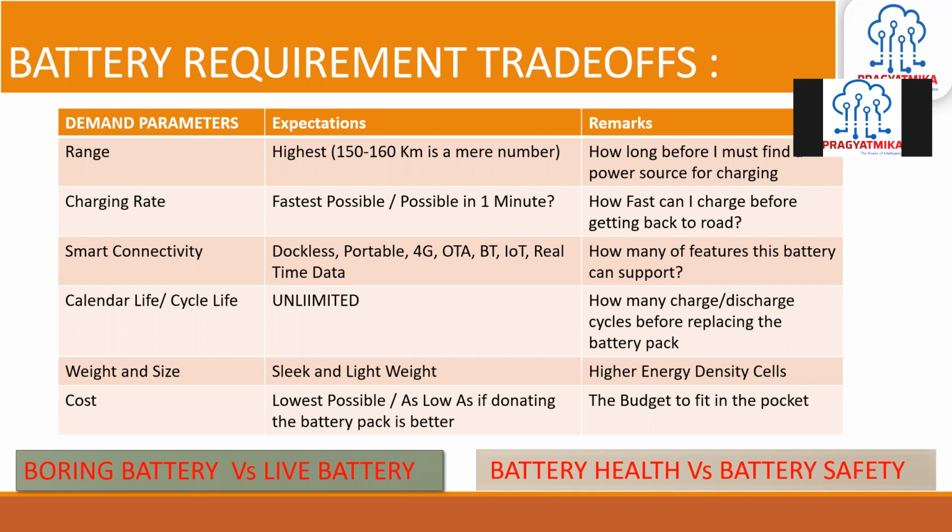I'm not saying that it is only due to charging, but there is a higher chance that if you are not following those charging profiles, the performance, the safety, and the durability of your battery pack are all compromised. So whether you are giving fast charging in your battery pack, it is at the cost of your performance, or your safety, or your durability.